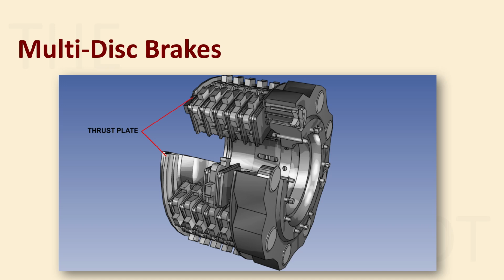See closely. This thing that you're seeing here is your piston, right? These are your pistons. Now what is happening is that when you apply brakes, the hydraulic fluid will be rushed in and it will push these pistons. So the forces will be applied on these pistons, and the pistons will move inwards. The pistons will then apply force on the pressure plate. This is your pressure plate, right?